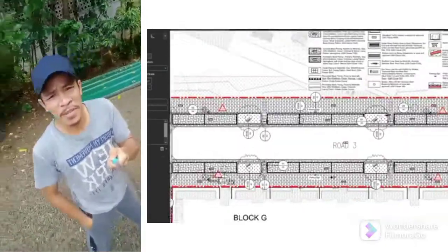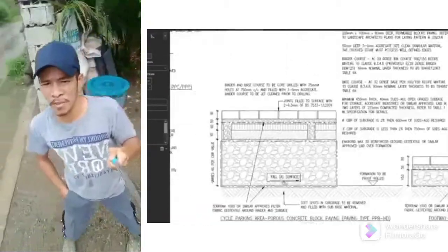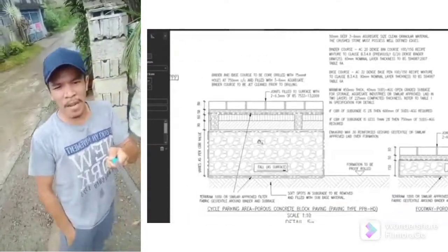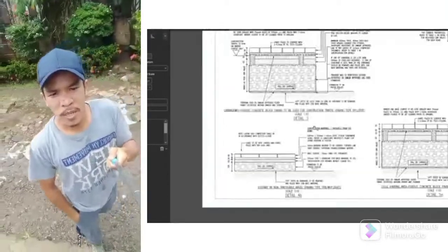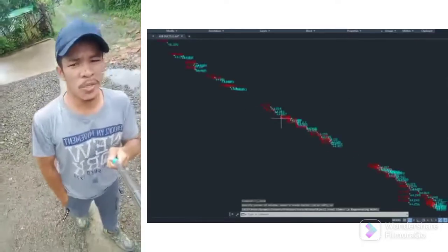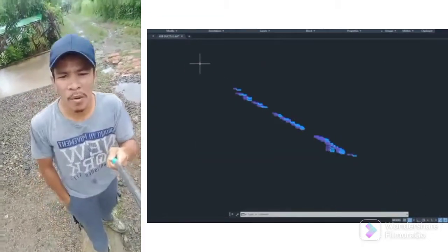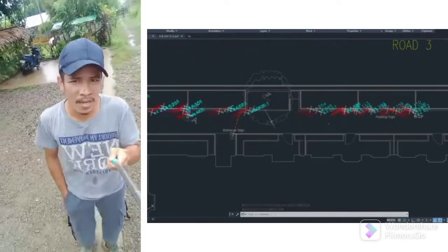Setting out is the reverse of surveying, which is the process of locating points for columns, site boundary levels, pile positions, and other necessary structural parts according to the construction drawings. Errors should be avoided because the whole structure will be built based on the respective setting out.